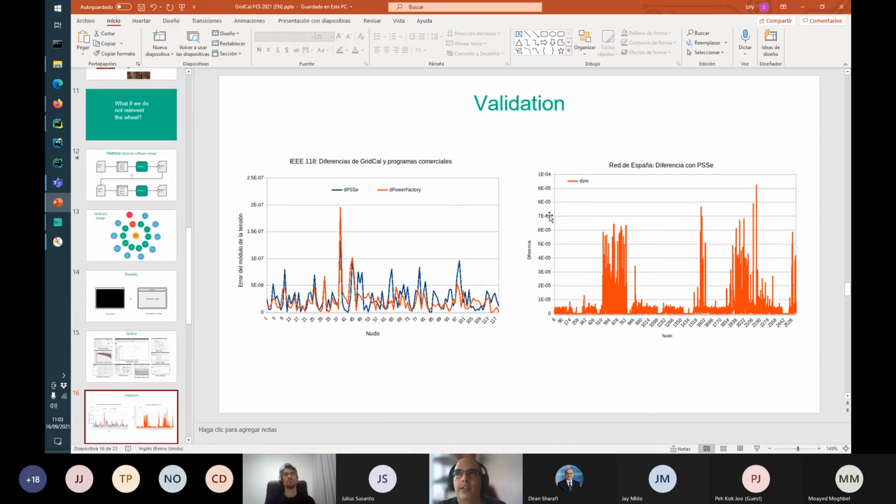What is the disadvantage or difficulty in checking this? That the options, whatever they might be, you go to PSSC or Power Factory, there are 1,000 options. You go to GridCal, there are 1,000 options, and probably they are slightly different. So you need to make sure that those options actually mean the same for the numerical algorithm to make the comparison.